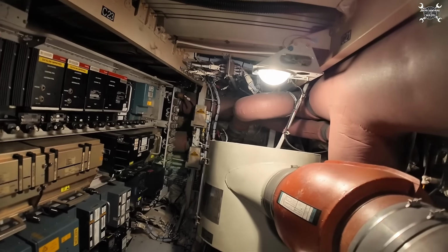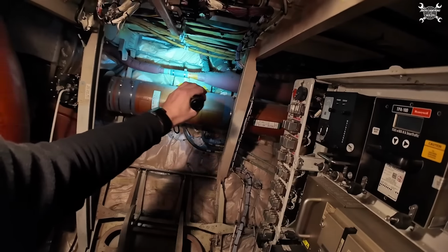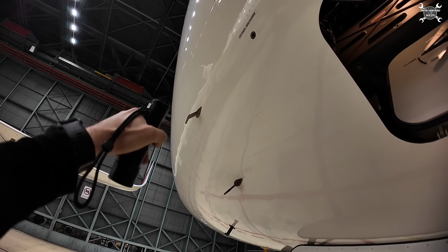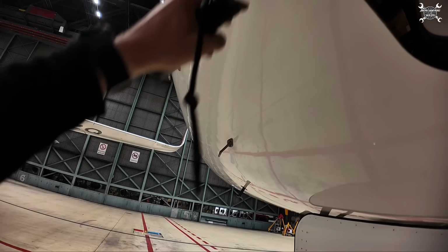As I said before, each air data module provides information to its own ADIRS. In case of those 2, which I showed you over there on the left side of the airplane, you have captain and FO, which means captain to ADIRS 1 and FO to ADIRS 2. Here behind me, you can see air data modules from the right side. And now let's take a look at the ones which belong to pitot probes. Here you can see the pitot probe which belongs to ADIRS 1 or to the captain. And this one is standby, or it belongs to system number 3.